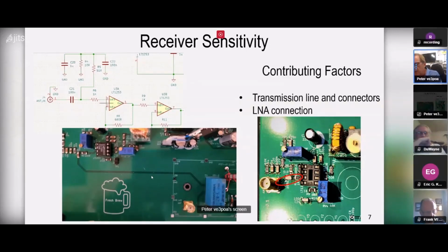Okay, the potential sensitivity it's possible to achieve with a given noise figure is determined by the IF bandwidth required. For example, CW or sideband, choose an IF bandwidth just wide enough to pass the desired signal, and this maximizes the signal to noise ratio. At the moment with Phoenix, we have a 4 crystal IF. Early on, I was beginning to think that maybe we should have gone to at least 5, but somewhere along the way, I'll start playing around with crystal filters again and go up with more crystals in there and see how they look.